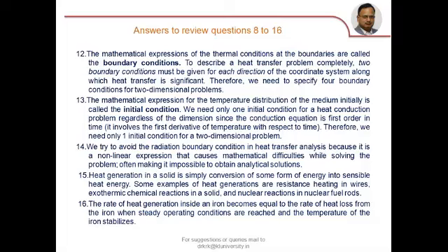So minus kA dT by dx at the surface is equal to sigma A Ts to the power 4 minus T infinity to the power 4. See, the fourth power is involved in that. Because of that fourth power, the equation becomes nonlinear and we face a lot of difficulty to obtain an analytical solution. So generally, radiation boundary conditions are not preferred in heat transfer because of their complexity in solving the problem.